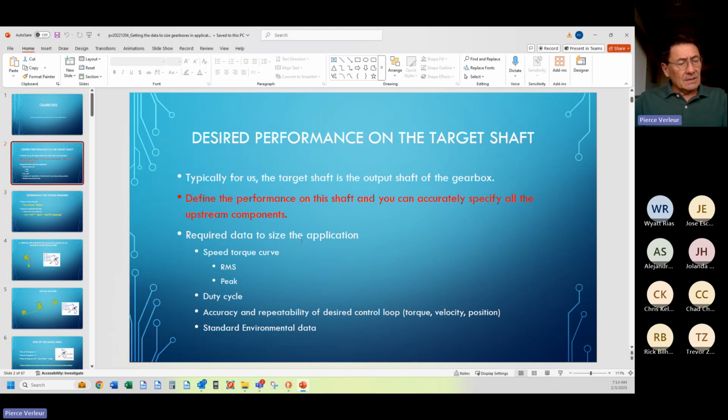For example, if you have a very high repeatability, and let's say your accuracy is plus or minus, as I said, 1/10 of a degree, but your repeatability is really high, so you always land on plus 1/10 of a degree. You're within the accuracy range, but your repeatability constantly hits that. It doesn't get to zero. It doesn't get to minus a tenth of a degree.